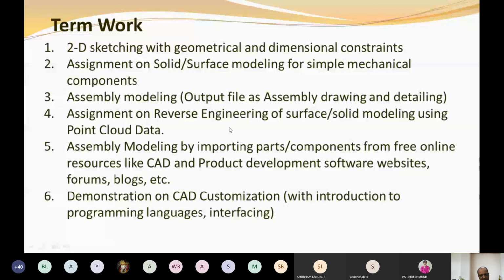In that case, how to draw the rectangle? Either by giving the rectangle command or by giving a simple line command 4 times. So what are the input parameters required? Say, the coordinates of two opposite corners. This will be the input for that program, and you can write different commands depending upon your input. When you give the opposite corners, it will draw the particular rectangle.